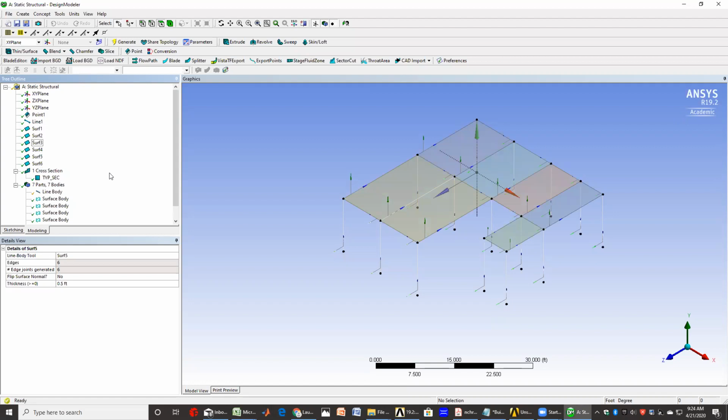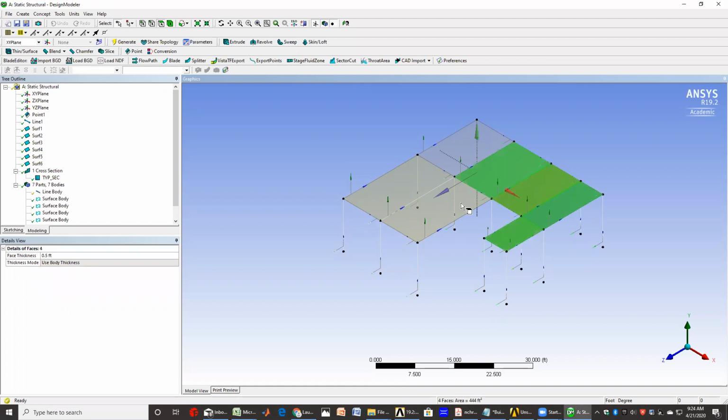So I have all my surfaces given like this. I'll apply later pressure on these surfaces, so I want to make sure that if I pick them, that green color will come, so that basically all the normals for these are as such.